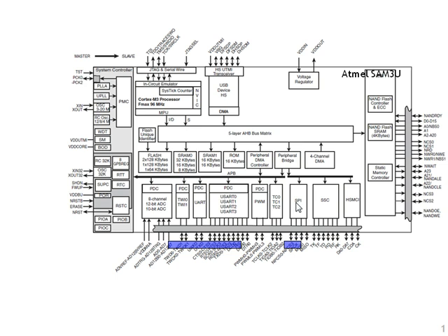The chips typically have a clock they need, and they will give you what's called synchronous, because it's got a clock, serial communication, and that can be very high speed. The UART with its serial port interface can give you what's known as asynchronous. That means without a clock distributed serial communication.